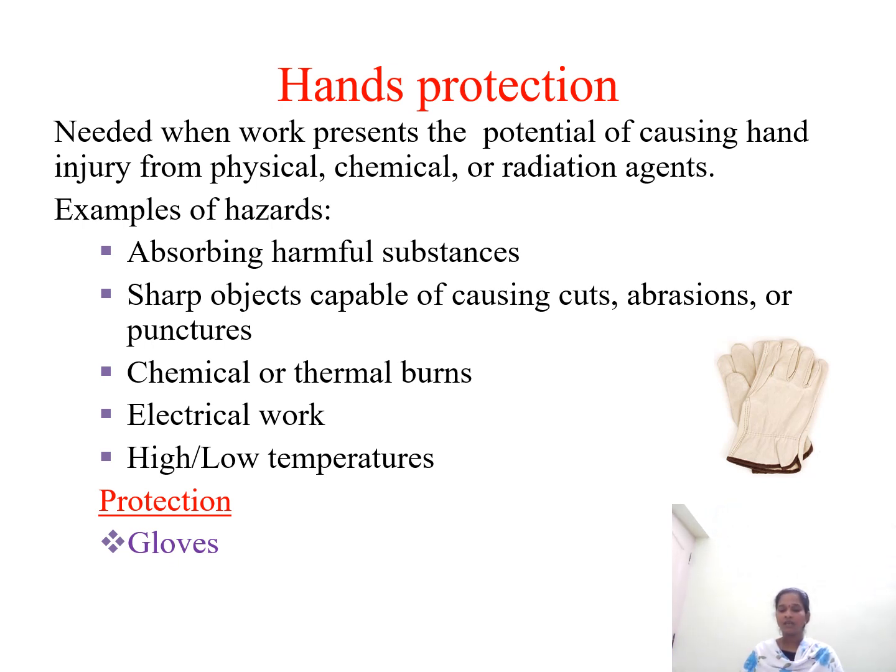For example, for a chemical hazard, we should choose a compatible material that suits all chemicals. Gloves come in different forms: disposable gloves, fabric gloves, chemical resistant gloves, metal mesh gloves and aluminized fabric gloves. Disposable gloves protect against mild irritants, whereas fabric gloves protect and insulate against heat and cold. Leather gloves are used to guard against injuries from sparks, whereas chemical resistant gloves are used to protect against chemical exposure.